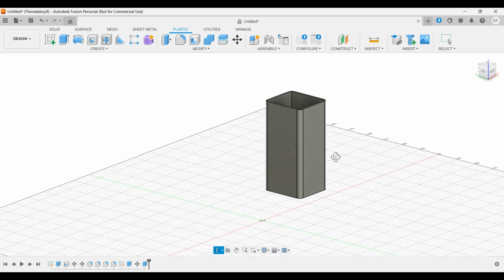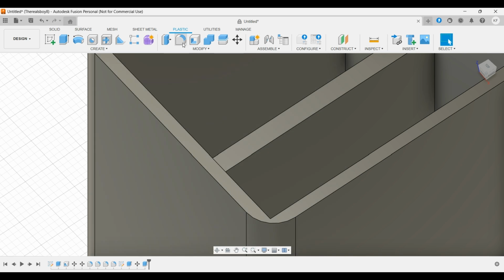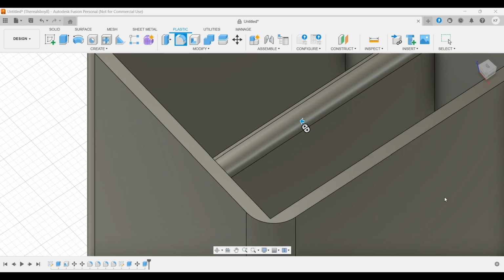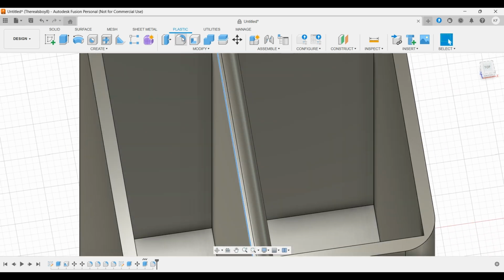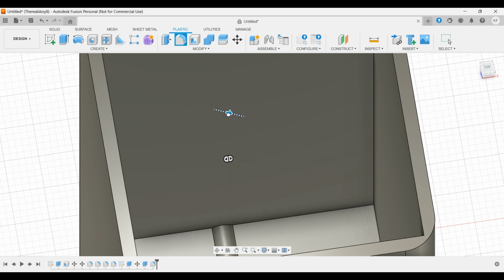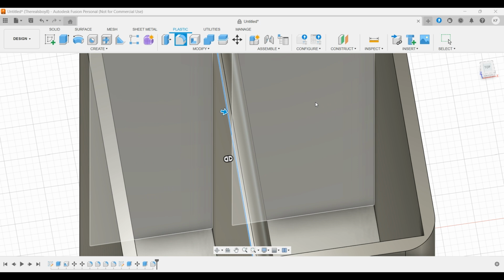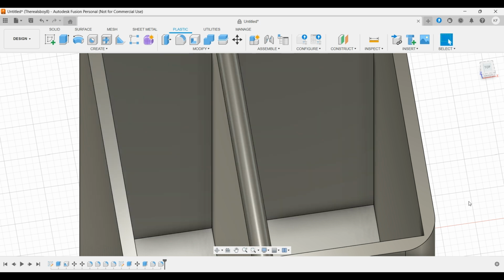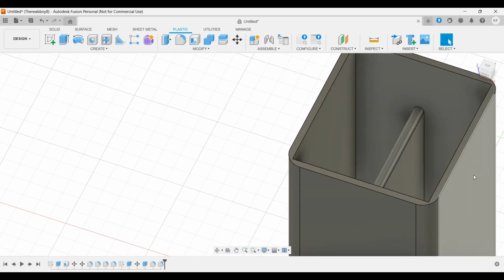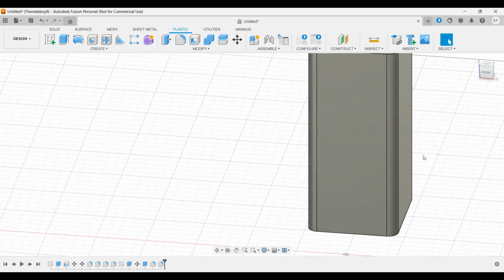Right. So these are pretty much the basics. Again, we can also fillet these edges here just a little bit by 2.5 millimeters. That'll give us a nice aesthetic to our thing. All right, let's go actually 1.5, and boom. I have a nice rounded edge, which will be very good for putting pencils, erasers, anything you need.